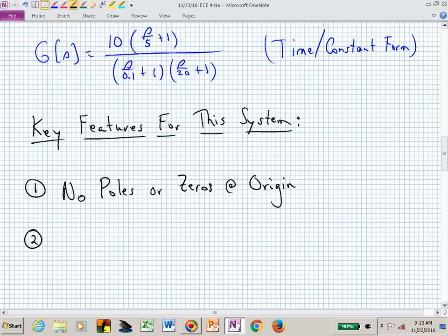If we had just one pole, what would our magnitude plot be doing? It's sloping. Which way is it sloping, up or down, and how fast is it sloping if I have one pole? It's going down since it's a pole, and it's going down at 20 dB per decade. So when you're finishing your Bode plot, at the end where you're doing the magnitude, it better be sloping at minus 20 dB per decade at high frequencies. Let me write that down. So here I have a pole zero excess of 1. Those are some of the key features.